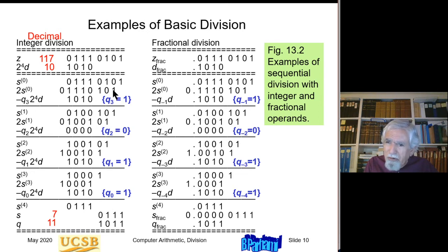And there's never any mix-up between the digits of the two things, because this part of the register never enters into an arithmetic operation. Only the upper half is operated upon. Okay? So those bits can coexist. The bits of the partial remainder and the bits of the quotient can coexist in that part until eventually the quotient takes over and occupies the entire lower half.